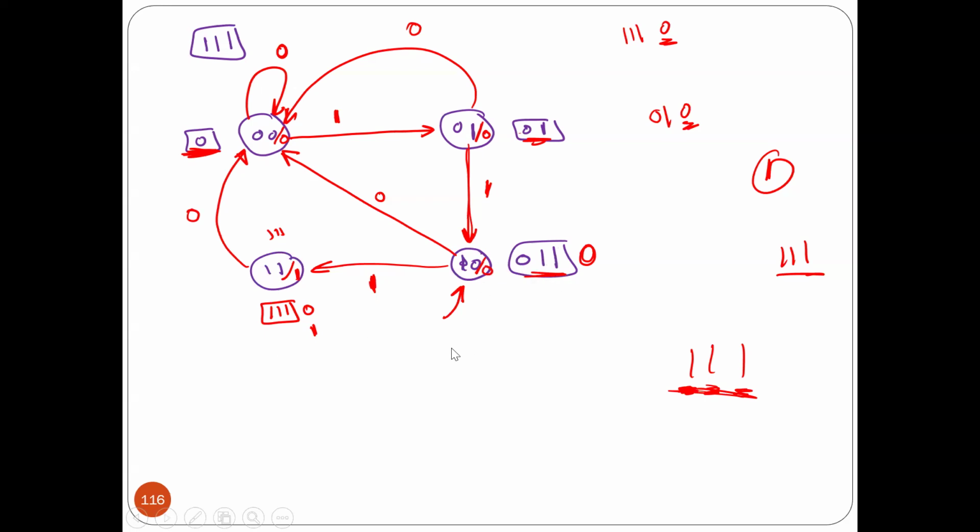Okay. Now, the other case, after receiving 3 ones, I got 1 more. What should I do? Yes, I have to look here and output 1. By doing that, that means if I receive 1, 1, 1, I'm going to output 1, and then here, if I receive another 1, I will stay in this one because I'm allowing overlapping. If you are in this state, I will reduce because of this one here, I will reduce another 1. So as long as you receive 1, 1, 1, 1, you are going to continue in this state.